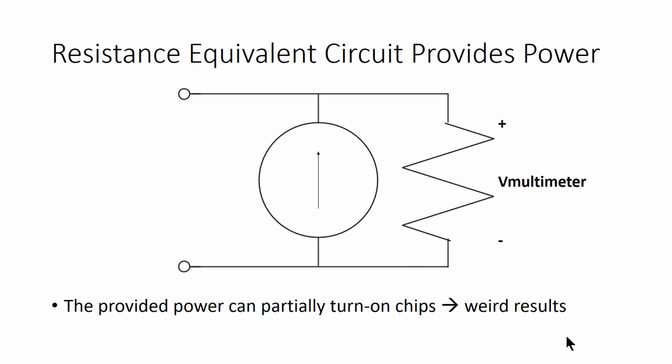The equivalent circuit for resistance mode is a big resistor, just like the voltage mode measurements. The only difference is that in order to measure a resistance, your multimeter needs to actually supply power to the external circuit. This measurement works by shooting a little bit of current out through your terminals into the world and observing how much voltage develops across the multimeter as a result. Because it knows how much current it's sent, it can relate the voltage it observes to the resistance out in the world. Because you want all your current to go into your circuit under test and not your multimeter, you use really big input resistance on your multimeter again, so that's the 10 mega ohm resistor that's pictured in this figure, just like for a voltage measurement.